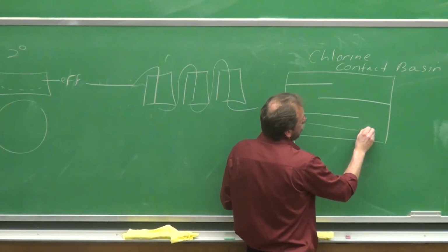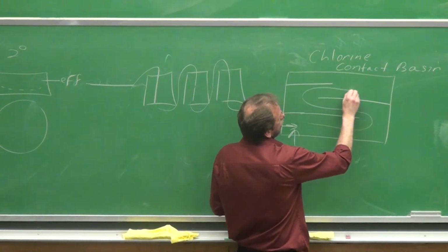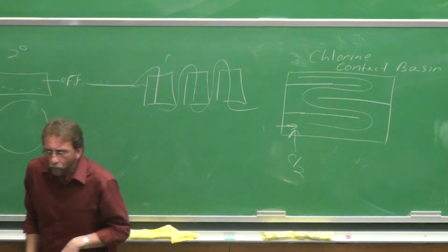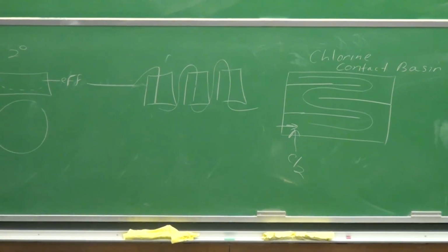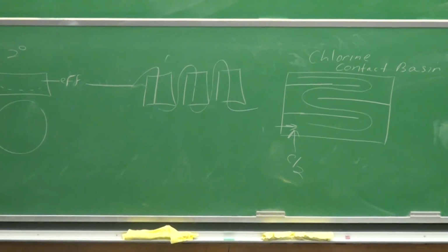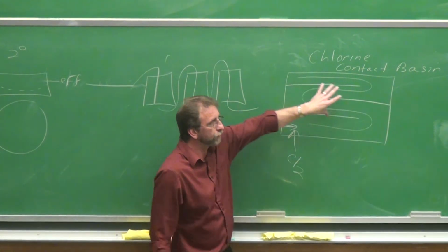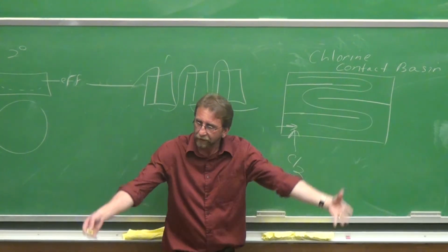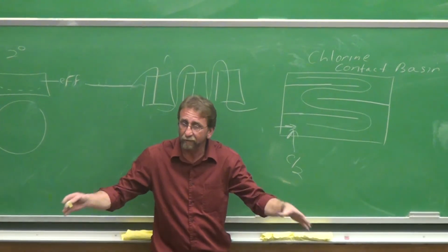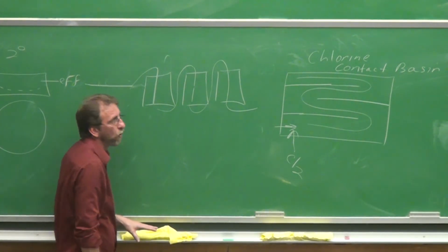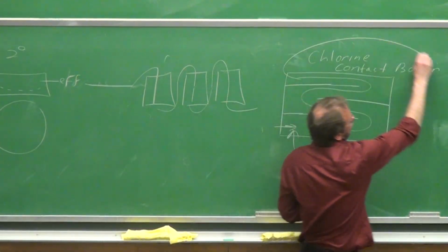So the water will flow through this contact basin, like so, with a contact time of about 2 hours. It takes about 2 hours for the water from the moment it enters into the contact basin to flow through the contact basin. It has been determined that about a 2-hour contact time is what it takes to kill most of the bacteria that's made it through that point. Then the water makes its way over